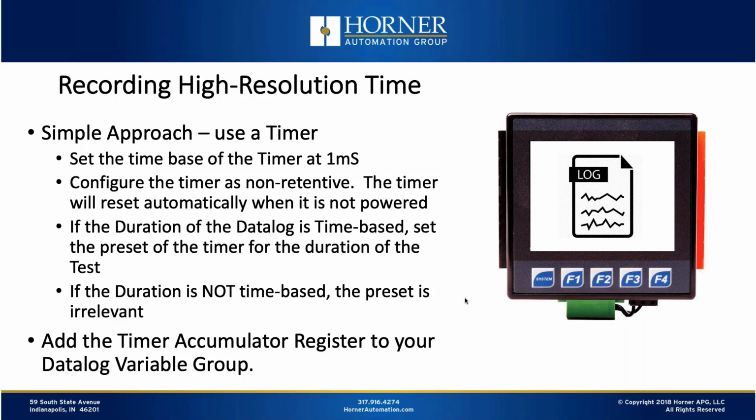So I'll show you how you can very easily add a time base of, let's say, milliseconds to your data log that will allow your data log samples to have more meaning in terms of the timestamp at least. Okay, so how will we do this? I'll show it to you in a second. But effectively, we're going to just use a regular old timer. We're going to set the time base of the timer to 1 millisecond. So the accumulator of that timer is going to be in terms of milliseconds.